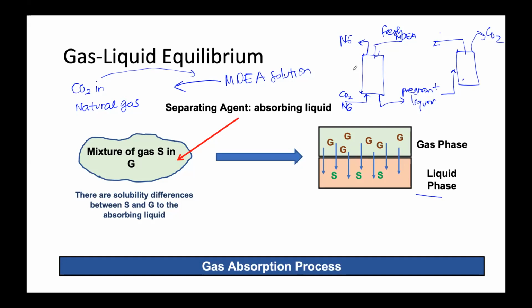For example, if we calculate that it is half a meter for one step of separation, and we need, for example, 20 steps of distillation, then we just multiply half a meter by 20 stages, so around 10 meters. Okay, so that's why the distillation column, also the absorption column, is quite high. Yeah, so it's like a tower.